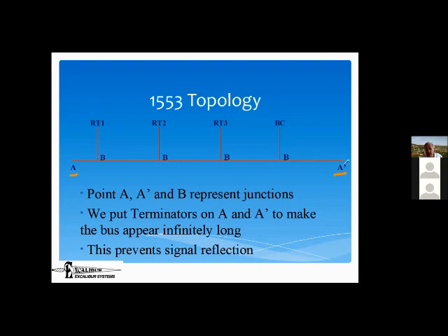So the terminators do that, which is why it's so important to put terminators on your bus, because otherwise they'll generate noise. And the problem with noise is that it sometimes causes parity errors, it sometimes causes other errors, and it sometimes does not. So you may get away with it for a while, and then all of a sudden it'll stop. So we've had cases where people haven't wired things exactly the way they should, and they work perfectly well.